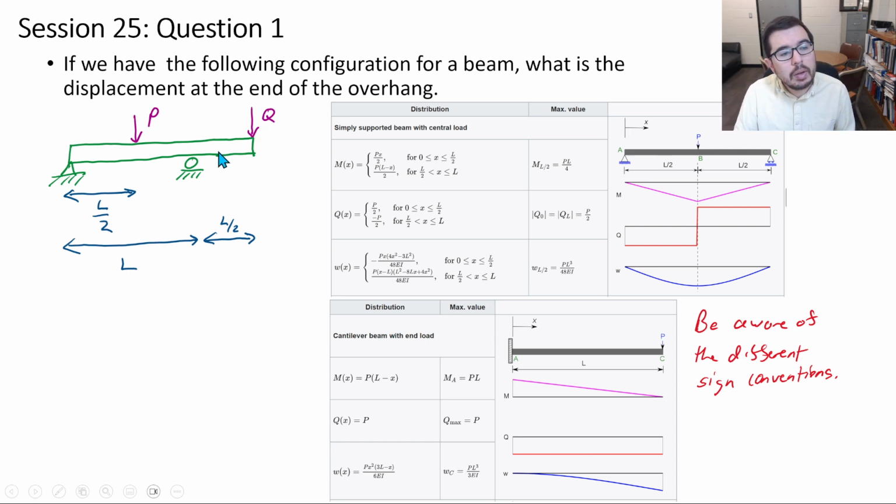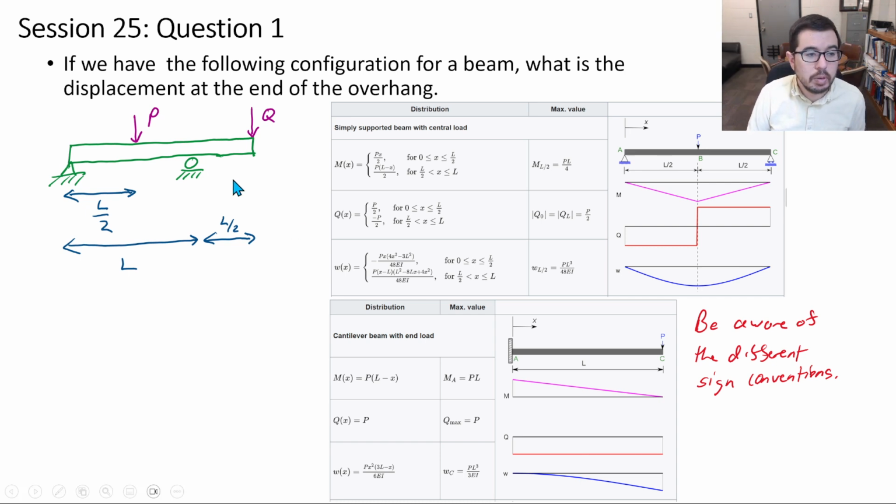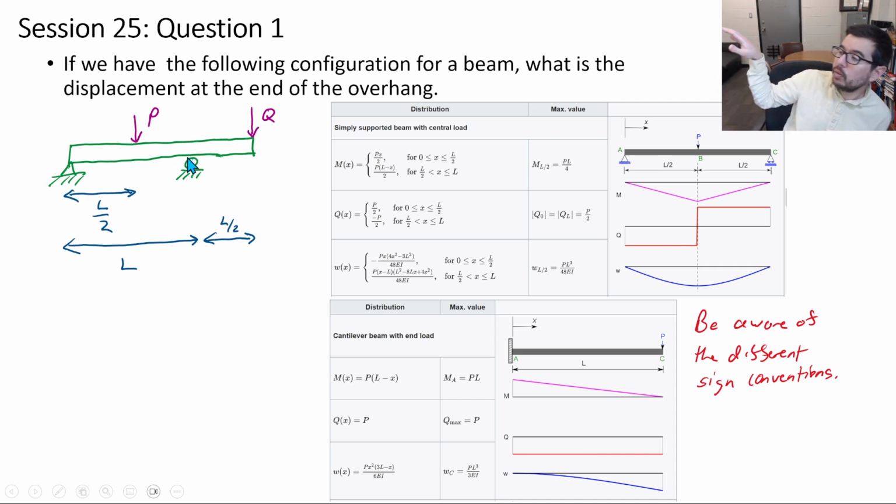And with that positive angle, now the question is, what do you treat this member as? Well, you say, okay, it has a slope, so if it were a rigid member, then I could project up to where it's going. But it's not a rigid member from here to here. It's essentially a cantilever member because there's material here, okay? So you figure out what the slope is, and then you've got a cantilever that's projected out, but it's also bending down, okay?